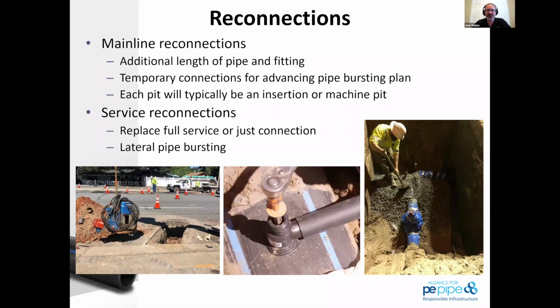So just to clarify, we had a question about the gouge thickness as well. It's 10% of the wall thickness. So that changes with the pipe size and the DR. So once you get the actual wall thickness of that pipe, then that would be 10% of that itself. Lots of different ways to be able to do these, lots of proven connections.